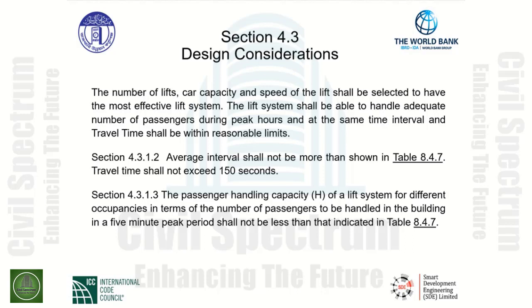The next section is called handling capacity. It is section 4.3.1.3 that reads the passenger handling capacity that we note as H of a lift system for different occupancies in terms of the number of passengers to be handled in the building in a 5-minute peak period shall not be less than that indicated in Table 8.4.7. Again, another reference to Table 8.4.7.